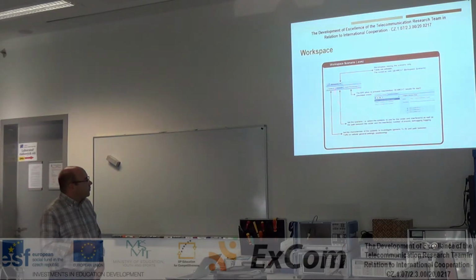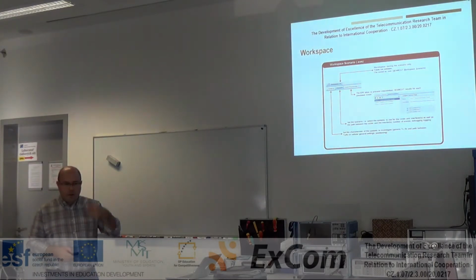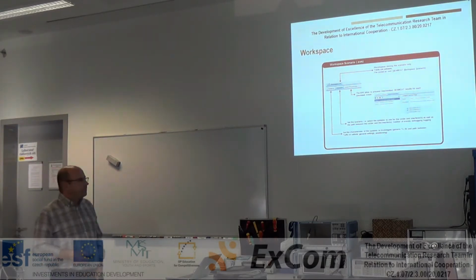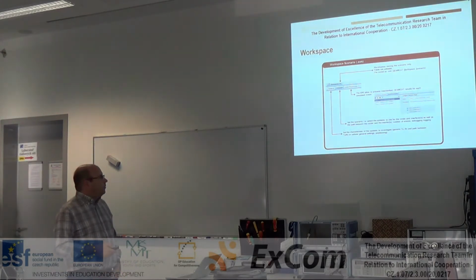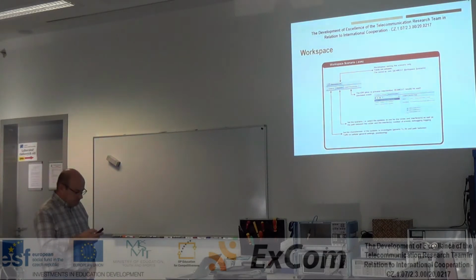The Systems tab is where you set the properties of the systems to investigate: power, antennas, height of the systems, so everything has to be defined here. On the receiver side, you also have to define the noise level if you want. The bandwidth can also be defined here.